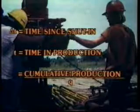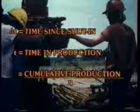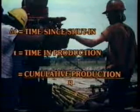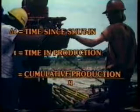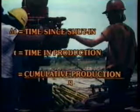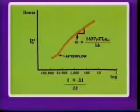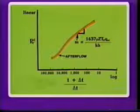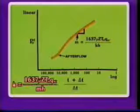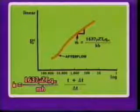If a well is produced at constant rate for a period of time, T, and then shut in for a period, delta T, we find that a plot of P sub W squared versus the log of T plus delta T over delta T is a straight line with slope M. The slope must be measured on the straight line portion, not during the early shut-in periods when afterflow into the wellbore occurs. So, we see that either a drawdown or buildup test will give us the value of the unknown, K, but that the buildup test is preferred.